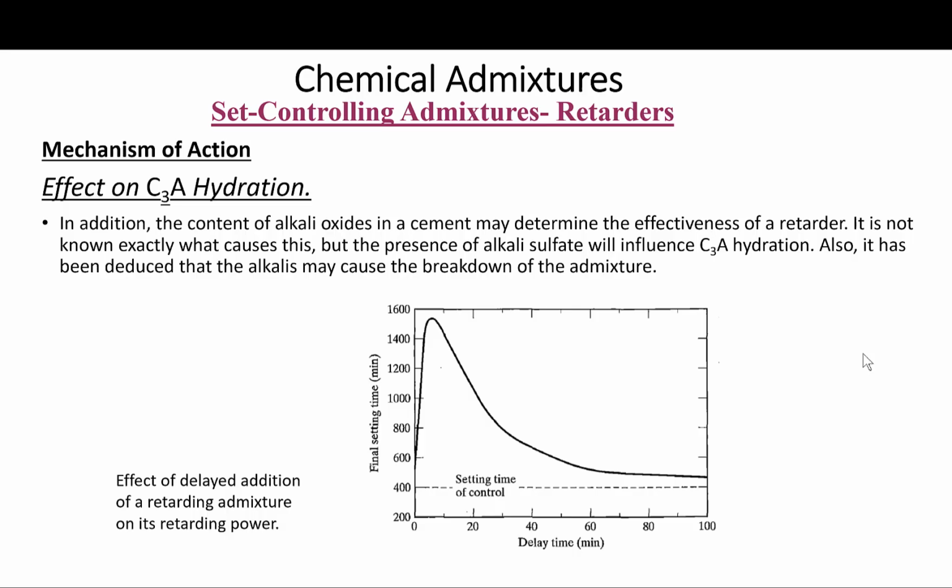Okay. Also, again, it has been suggested that an admixture cement incompatibility usually can be eliminated by simply changing either the cement or the admixture. So the trial batches and the tests, again, can go a long way in eliminating any unanticipated problems.